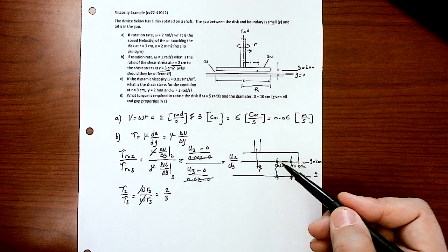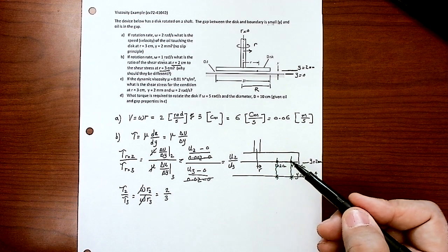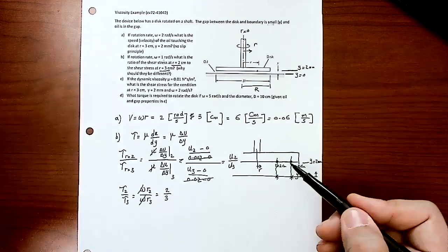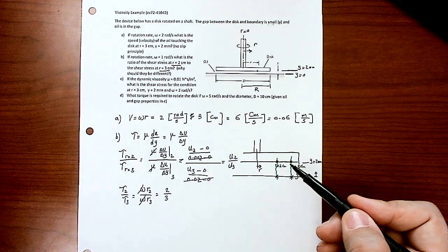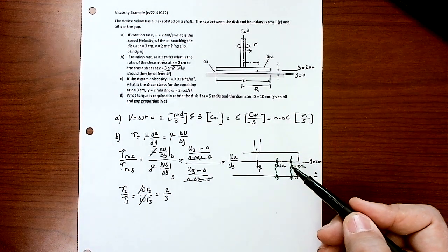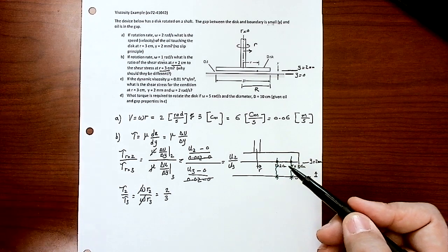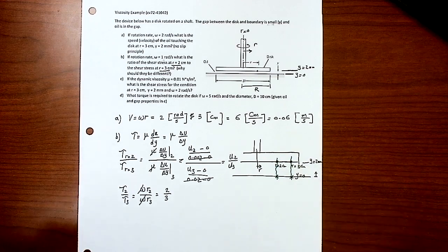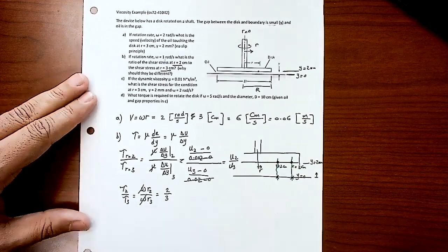Why? Because the more you go out, the centrifugal force is increasing, right? And to balance that, the shear force will increase and the shear stress will increase, right? We know that if you are holding a stone and you are tying the stone with a rope or a wire, then you start rotating it. The longer that rope or that wire is, the more force you'll get because the centrifugal force is increasing, okay? So this is answering part B, okay?